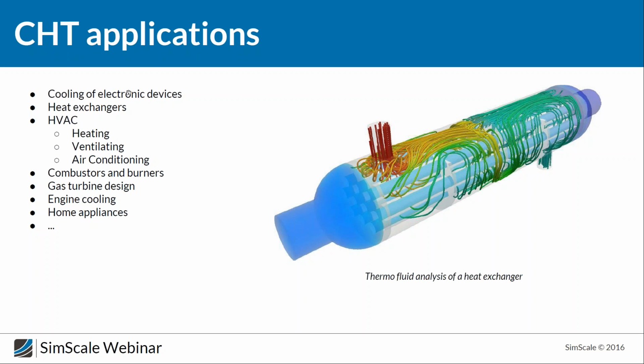Another very typical example are heat exchangers. We see an example that we simulated earlier on the right, on the image on the right. In this heat exchanger, what happens is that we have a fluid that, due to some process, has a higher temperature, and we want to cool it down. What we're interested in specifically in this example, we don't want to mix these two fluids, the fluid that has to cool down with the fluid that actually acts as the absorbing fluid. So what happens is that we enter, in this example, for example, water from one side of our heat exchanger, and run air through the outer chamber across the flow of the water. They don't mix because they're in different fluid regions, but they're connected through pipes which represent our solid region.